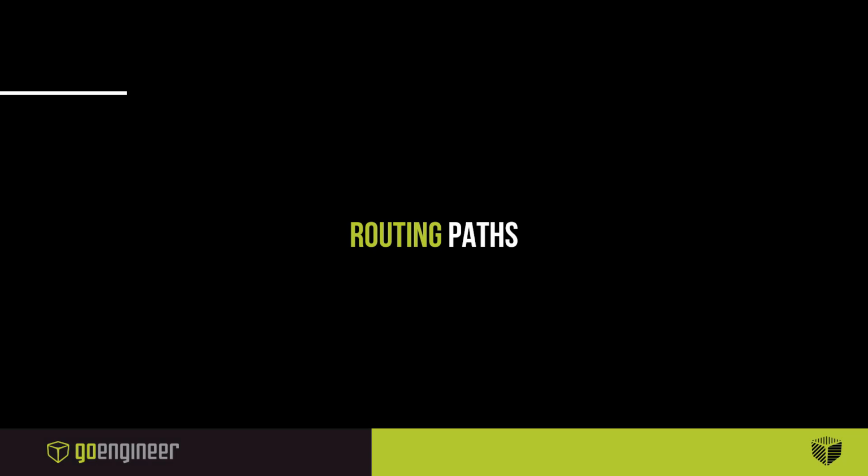Okay, so on to the 3D section. We have some additional abilities to define routing paths in SOLIDWORKS Electrical 3D. What we're able to do now is add arcs and splines to our routing paths. And just a little background, a routing path is a general guideline of where wires should go.